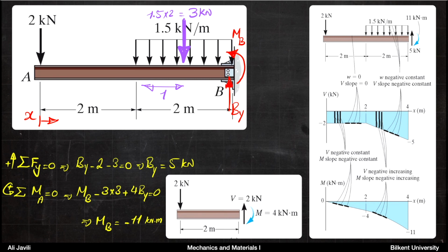Or, remembering the jump condition from the beginning of the lecture, the shear force here is 0, and coming from left to right, a concentrated force downwards gives a downward shift. So shear force is -2 at point A, and constant because there is no distributed load. Therefore the slope of V is 0 until you reach the center.